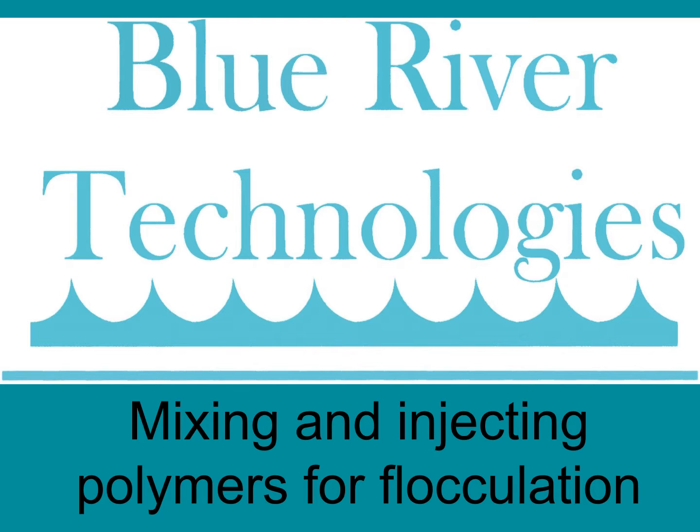The flocculation process is the single most important part of the geotextile dewatering process. You must have the correct flocculant, and it must be properly applied in order for the bag process to work properly.